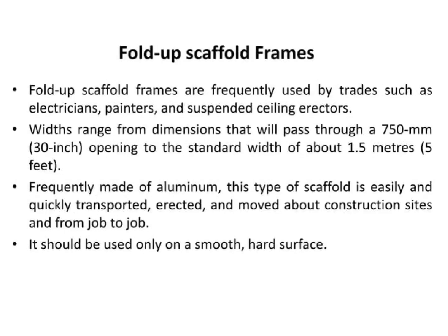Fold-up scaffold frames are an ideal solution for workers needing to access hard-to-reach areas. These frames are lightweight and easily portable, allowing workers such as electricians, painters, and suspended ceiling erectors to do their work quickly and safely. Available in varying widths, from 30 inches to 5 feet, fold-up scaffold frames are mostly constructed from aluminum. For the safest possible experience when using a fold-up scaffold frame, work should only be done on a smooth, hard surface.